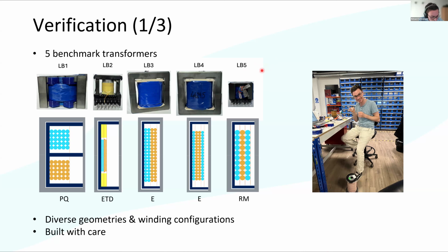And yeah, other difficulties if you want to measure leakage inductances with transformers with high transfer ratios: in general, if you measure from the side with a high number of turns, you have the problem of the reflected secondary impedance. And if you measure from the side with the lower number of turns, you have the problem that you want to measure very small inductances, which is again tricky. So sometimes you have to choose between those two and see what yields the better trade-off.